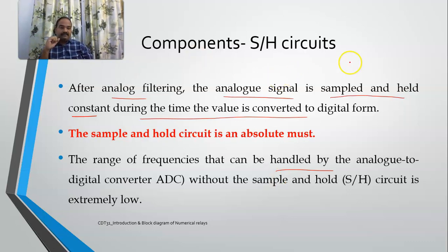So it is just like, let us suppose you have this data. Right. So the sample and hold circuit, let us suppose you want to measure the samples here. So what it does is it measures here, and up to this point, this data will be maintained like this. So instead of an increasing value, during this entire period, the data will be stored in this format.